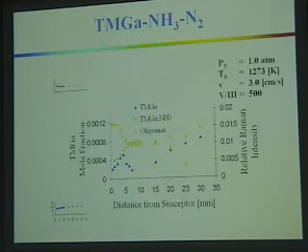Going one step further, if we now put in trimethylgallium separate from ammonia, separate from nitrogen, as you do in a traditional MOCVD reactor, you can see we form upstream very quickly the adduct trimethylgallium ammonia, but since there's excess trimethylgallium around, we can react it to start to form the oligomer up front. Then the adduct starts to reversibly decompose, to go back to trimethylgallium and ammonia.